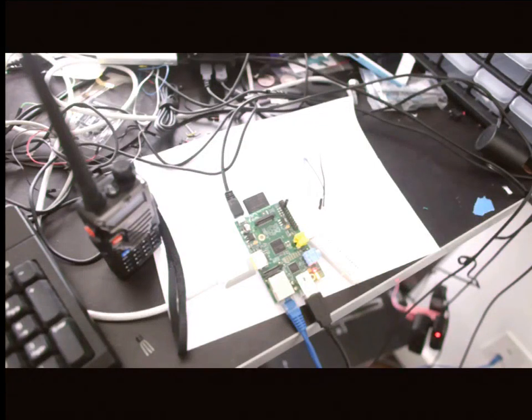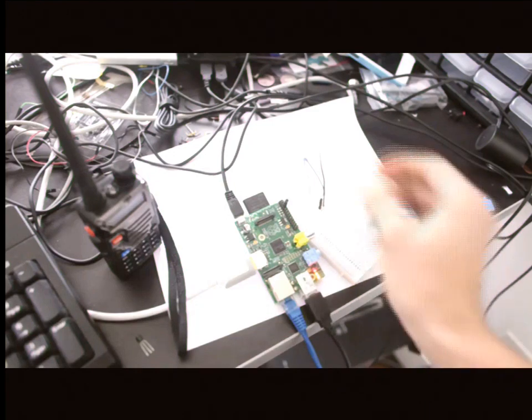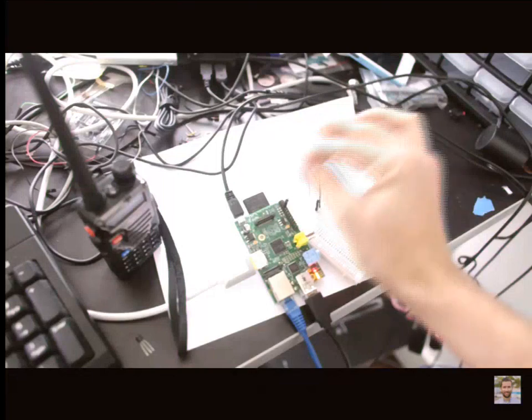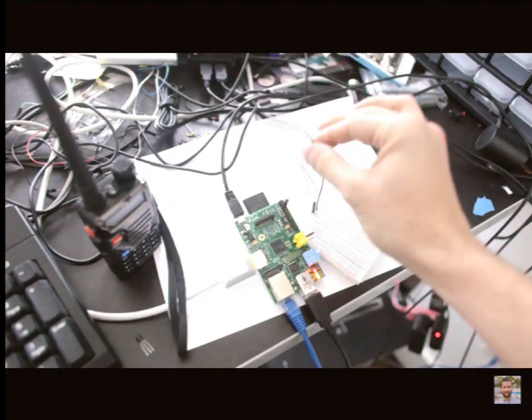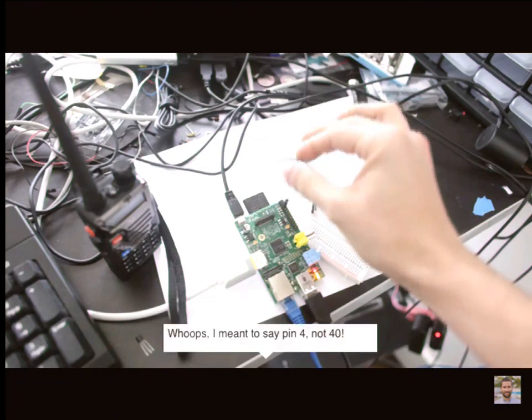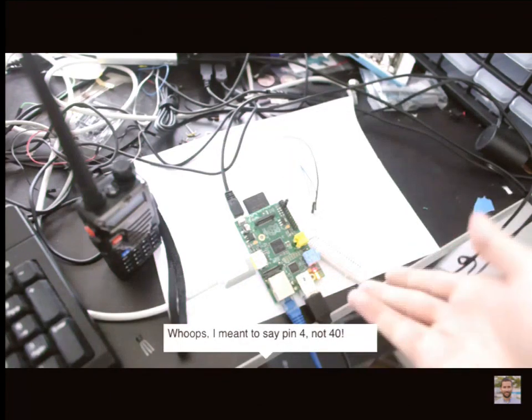The best part about this project, or the two best parts, one is that it's so easy to get running. You just use their code, you run it in Python, you give it a WAV file, and it just broadcasts it. The second best thing about this project is you don't need much hardware. This is all you need. This is just a piece of wire. I cut it to 20 centimeters, plugged it to pin 40, and I've got a personal FM transmitter.